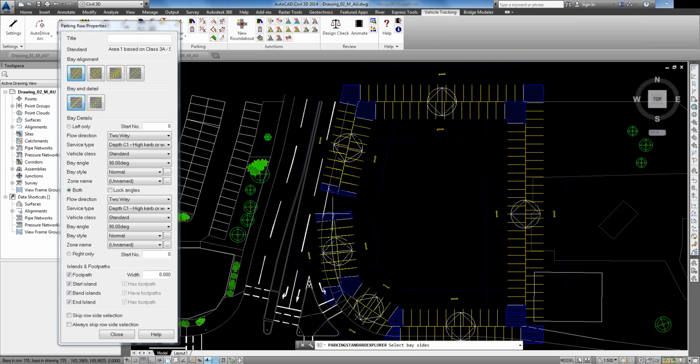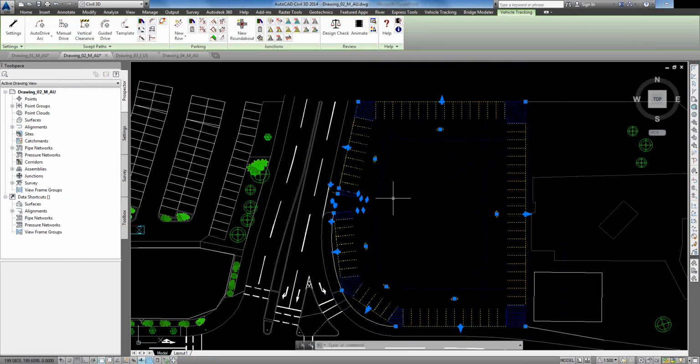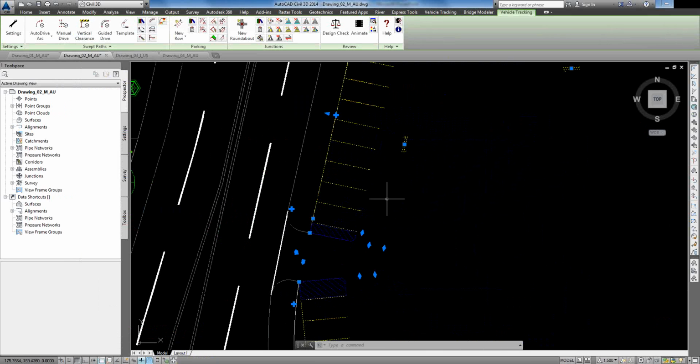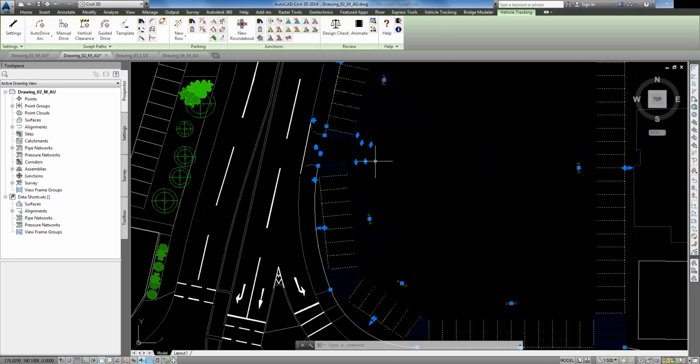drawing the perimeter, I then click enter, and the graphics then updates with the big arrows. Basically, they're saying, do you want it on the inside or the outside? I'd like it on the inside, and the graphic will change, and then it will complete and update it. You can see once it's drawn, it's actually one object, and it's automatically spaced and filled in all your corners, and it's even giving you an indicative aisle width there.